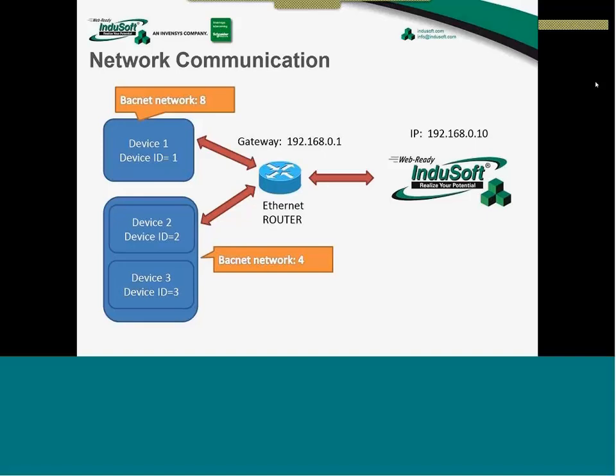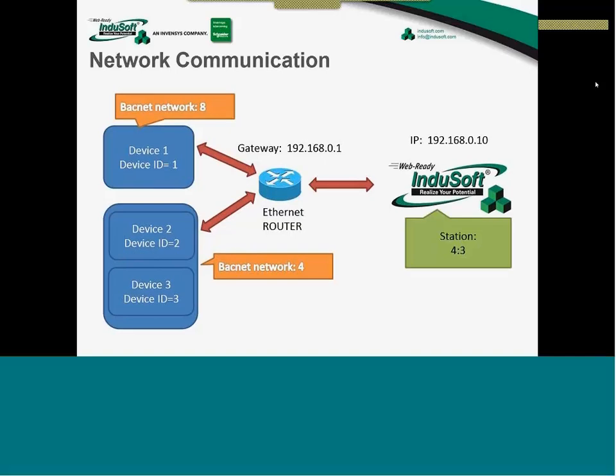Let's assume device 1 with device ID 1 is inside network 8, and devices 2 and 3 are inside network 4. Based on this case, how can you configure the station on BACnet? For example, you want to communicate with device 3 of network 4. So you put on the station of the driver 4:3.